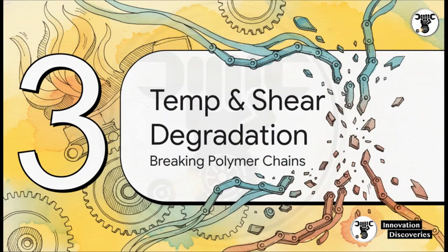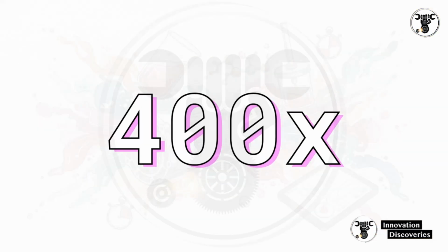Okay, Section 3. Temperature and shear degradation. We're talking about breaking the polymer chains. 400 times. That is how much higher your ATF viscosity can be at a minus 20-degree cold start compared to when it's at full operating temperature. We're talking 1,500 to 3,000 centistokes on a cold morning, dropping all the way down to just 6 or 8 centistokes when it gets hot. This drastic swing completely shifts the hydraulic timing window. And that right there is exactly why cold start shift timing issues are so incredibly common in the shop.